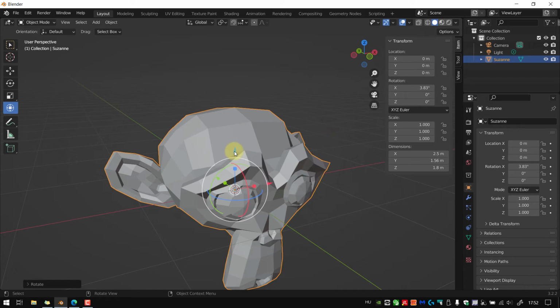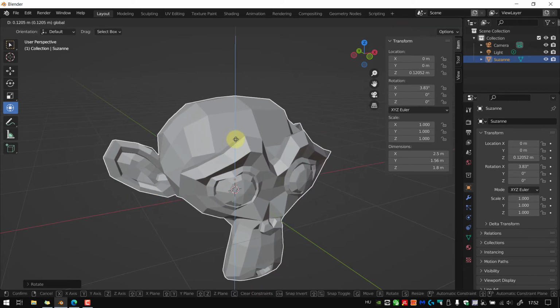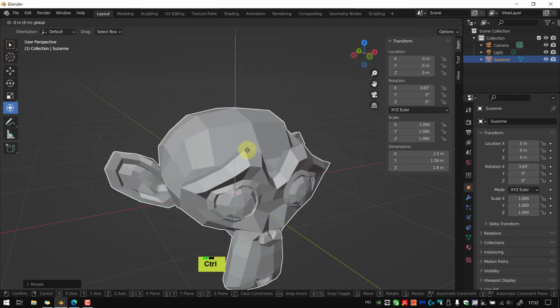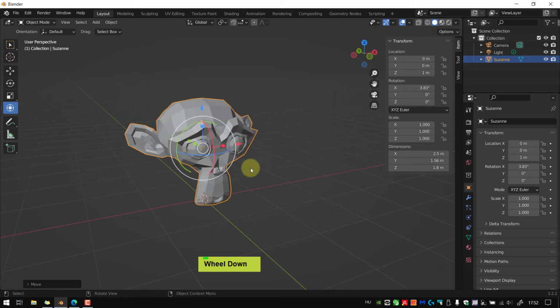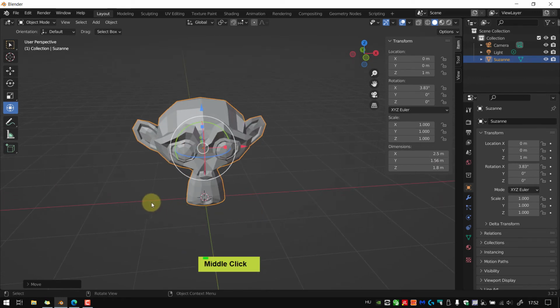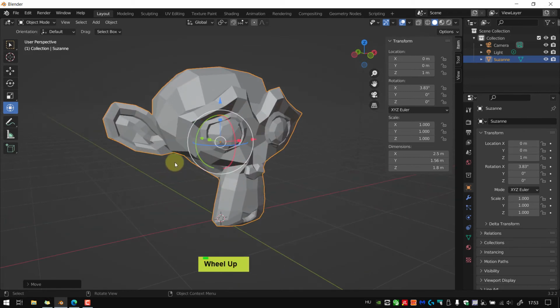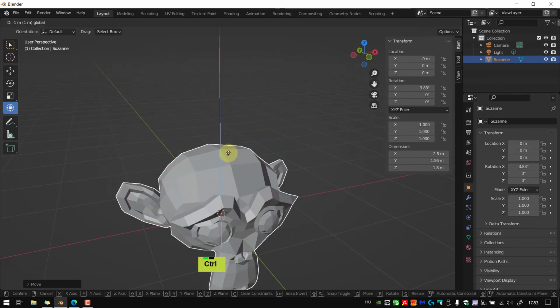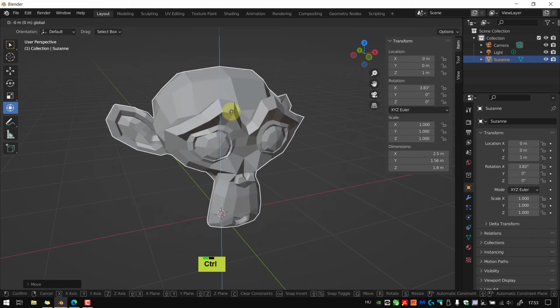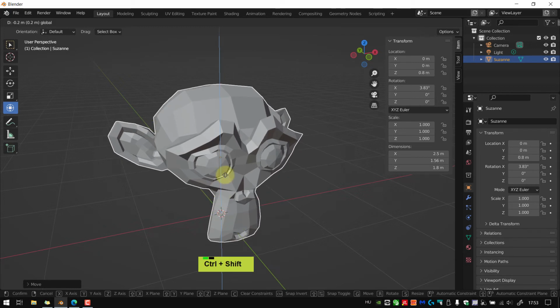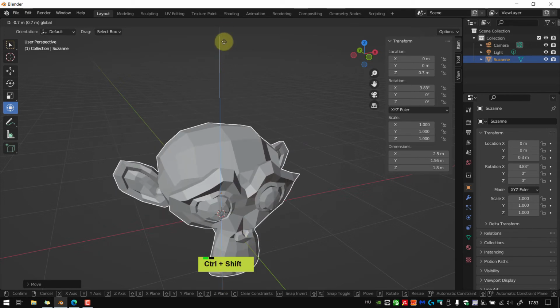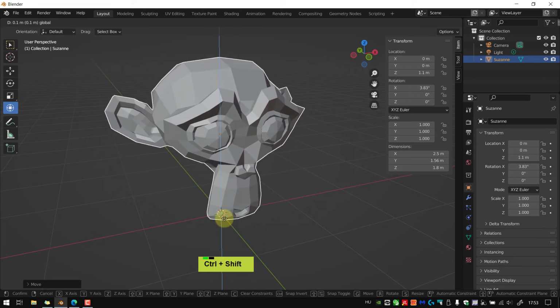All right, this same thing happens with move. When I'm holding the move and holding Control, it will move in grid steps. So what does it mean? This head is about 2.5 meters, so it looks like this one square here is 1 square meter. So when I'm using Control, it actually snaps to 1 meter. If the logic is true, if I'm holding down the Shift key, it may go in 10-centimeter steps. Yeah, 10 centimeters.